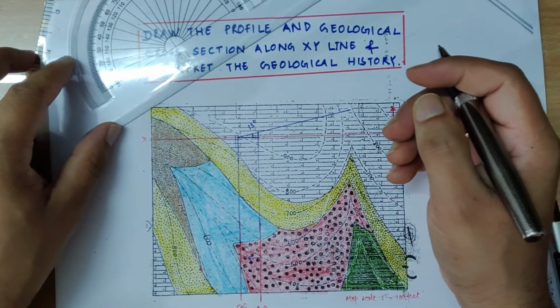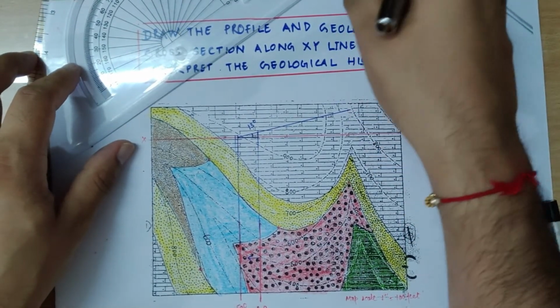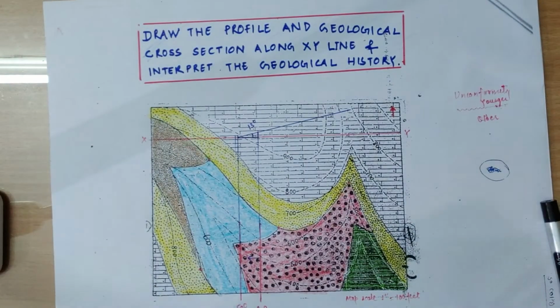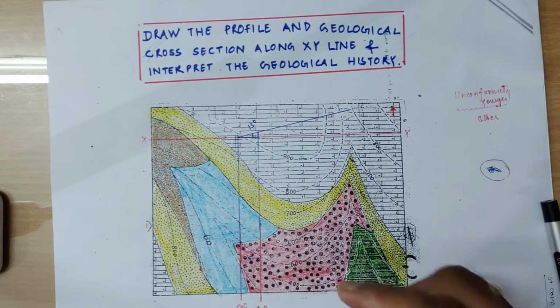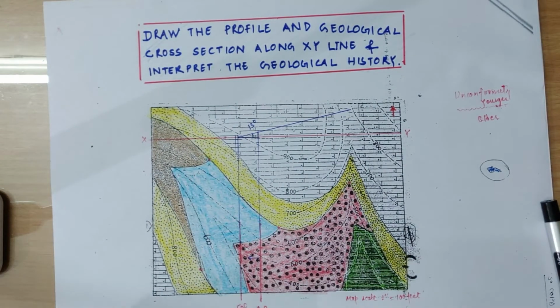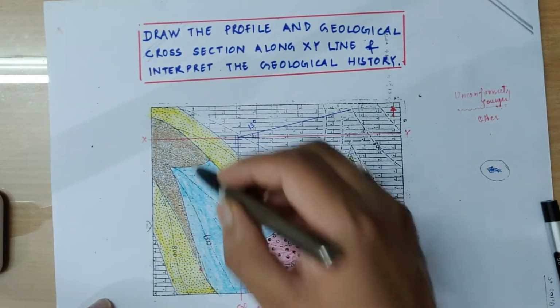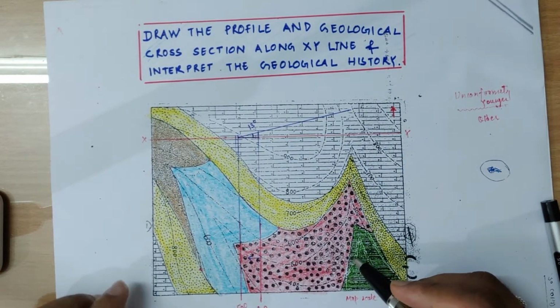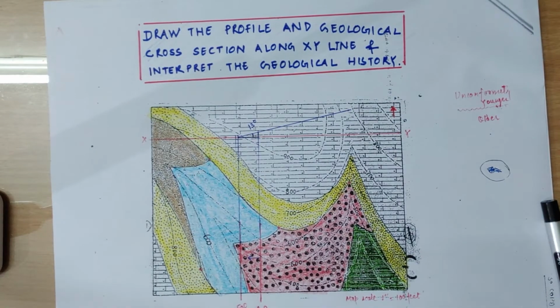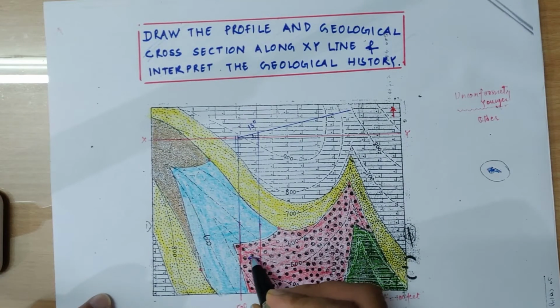Now we have to know the inclination of the younger sequence. So the older sequence contains 3 traces. It means the number of beds is 3 plus 1, that is 4. So here we have 4 beds and we have determined the direction of dip.